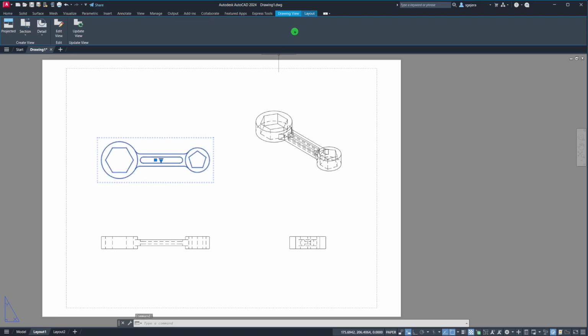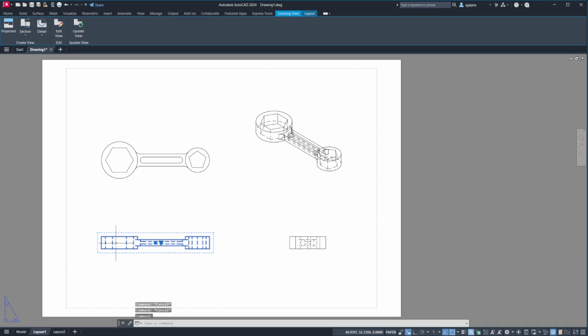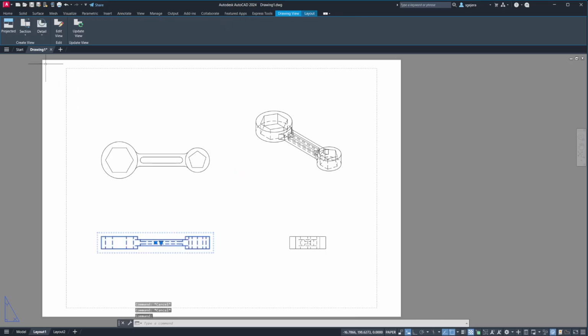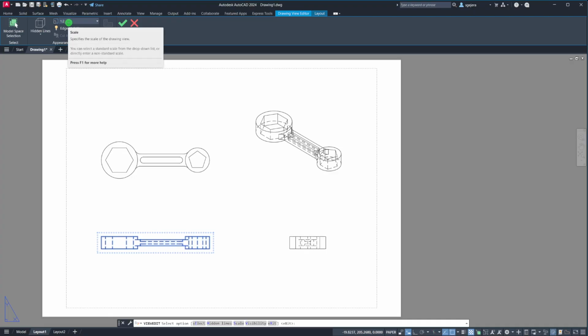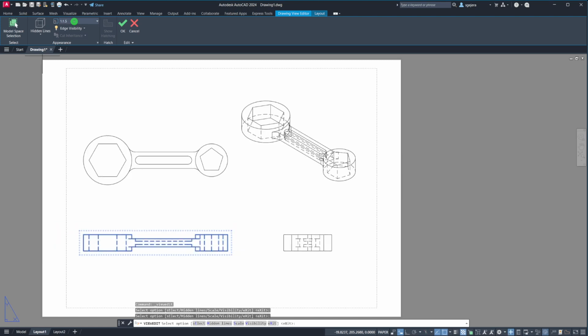And we can also see its size. If we double-click details, and let's do edit view, we can see what scale was used. It's 1:2. We can actually change this. So now if we do 1:1, it's too big. It won't fit on the paper. So 1:2, probably 1:1.5 will fit. 1:1.5 will also work.